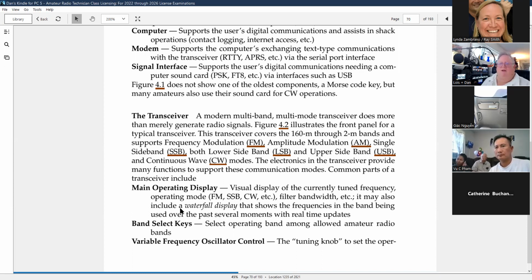On your radio, we'll have these visual displays of what you're tuned on. The waterfall, if you're still seeing my screen on the side, you'll see behind me, this is an extra monitor, makes it big for me. Down below that, it looks like water running down. This is low frequency and higher. Here's somebody talking, and it makes it very easy to visually know where I want to tune. It shows the frequencies in the band that I'm using over a short period of time.